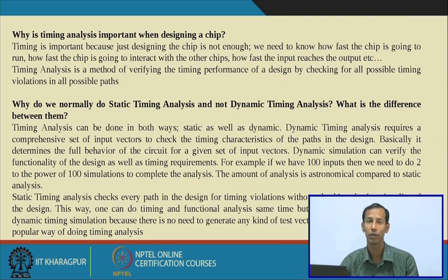That means in dynamic analysis, I can put some real-time test vectors or real-time data into the design, and then I can check, for this particular set of signals, what the timing requirement for my design is. So in that dynamic environment, I can do dynamic timing analysis.